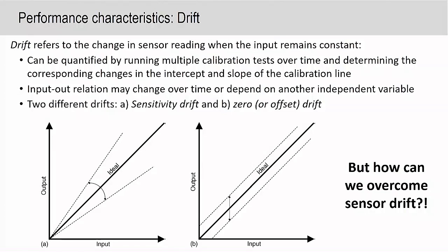But sensor drift is a massive issue for us because long-term implantable pressure sensors don't really exist. They typically have a membrane that will deform and then detect the pressure. This membrane can have tissue grow onto it, which is a really big problem. If you have tissue growing onto a membrane, it changes the deformability of the membrane and then leads to drift of the sensor.